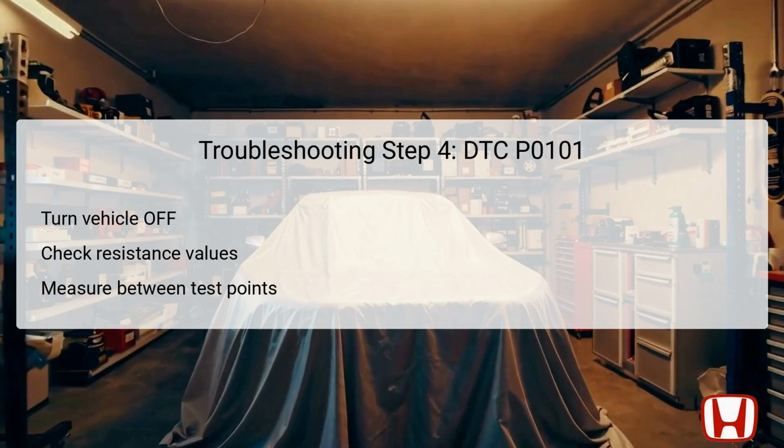If resistance differs significantly, it suggests potential issues within the vehicle ground or sensor line, which would then necessitate further inspection to locate the fault.